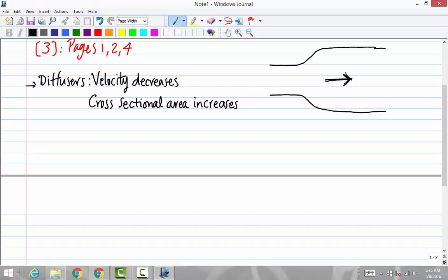The question asks for a geometric parameter, which is the diameter at the outlet. Whenever you're asked about the geometry of your system or design, you might need to take advantage of conservation of mass or conservation of volumetric flow rate, because as mass goes through your system, it can balance the geometry.